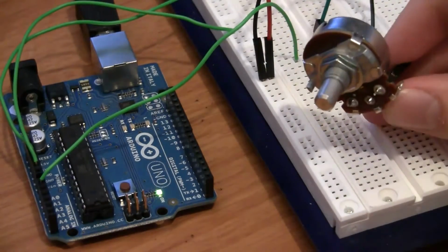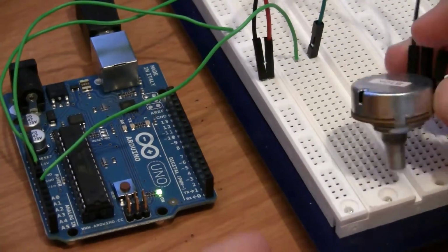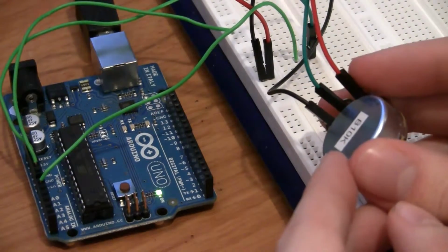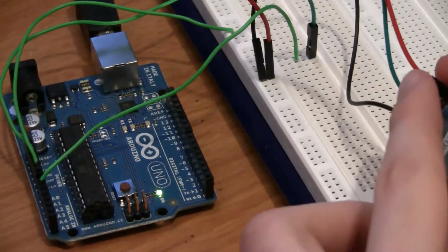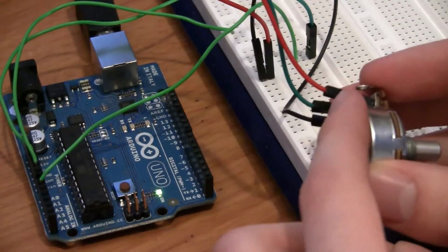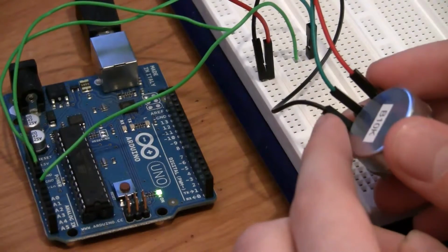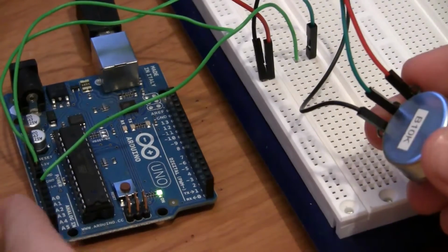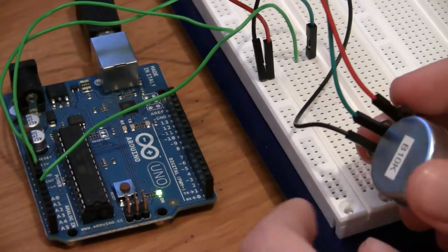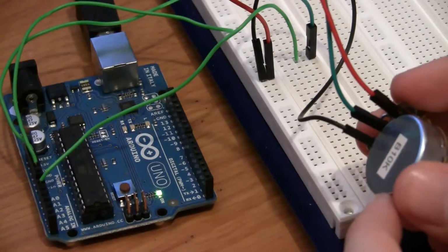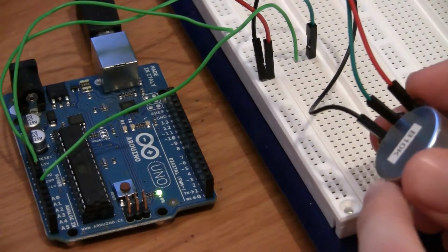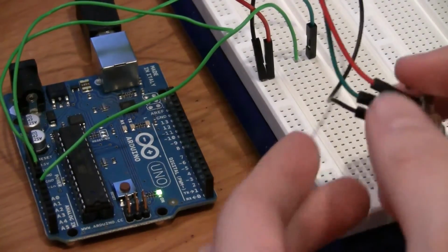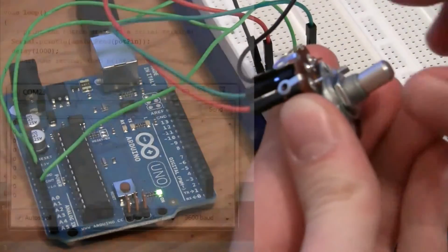Here I have a simple potentiometer, usually abbreviated to a pot, and I have it hooked up to one of the analog input pins on the Arduino. Now we'll be talking a little bit more about analog input in some future episodes, but basically we have our red connector on the pot, which goes to our 5 volts, ground, which goes to ground as I showed in the diagram, and then the middle one is the one going to the analog input pin on the Arduino, which is analog input 0. The Arduino has 6 analog inputs, each of which can read values from 0 to 1023 depending on the voltage from 0 to 5 that you give them. And you can change the voltage reference too, but we'll talk about that a little bit later. So, let's see what happens when I turn our potentiometer.